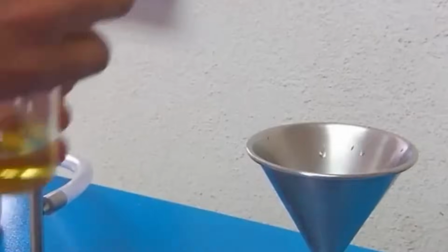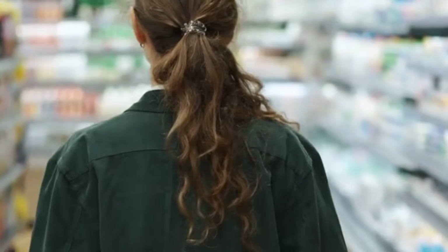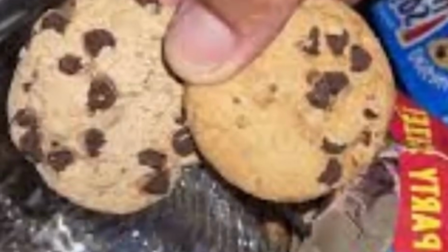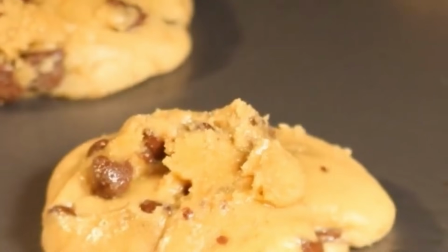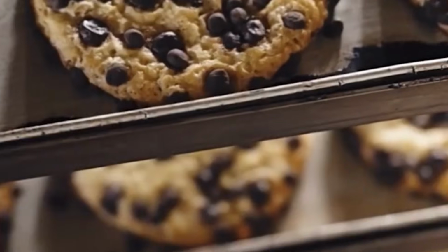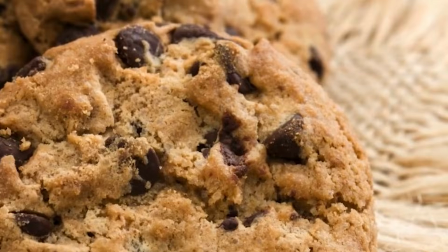Each cookie slug is pushed into a horizontal flow wrapper. Wrapping film is heat sealable and typically polypropylene based with a moisture barrier coating. The film unwinds from a roll and wraps around the cookie slug as it is propelled forward. Longitudinal and transverse heat sealers create the fin seal and end seals in rapid succession.